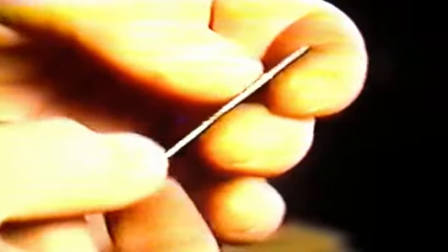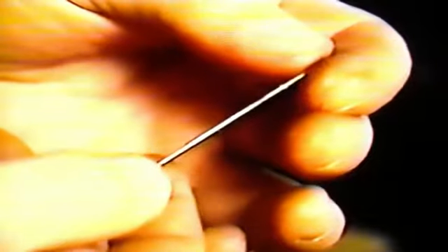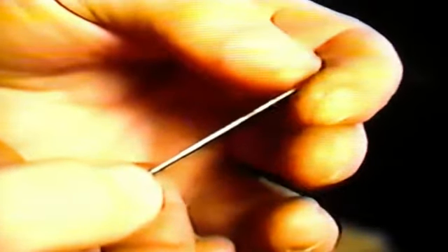After making the visual inspection, you're ready to remove the metering rods. Be extremely careful to watch for the fine springs which fit around the rods. They're quite thin and can easily be lost. More importantly, without the springs in place, the rods will just lay in the bottom of the jet and will not be able to do the job they were intended for. As you remove the rods, carefully inspect them for damage or bending. They, of course, must be perfectly straight to operate properly.